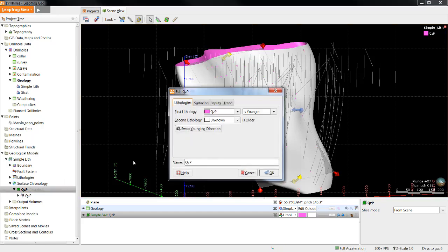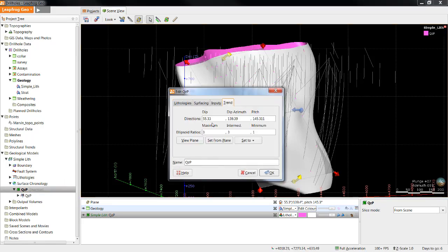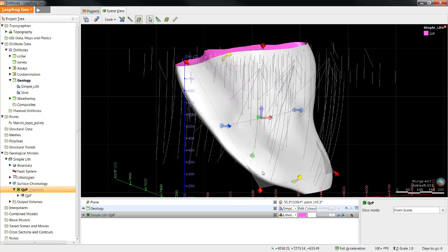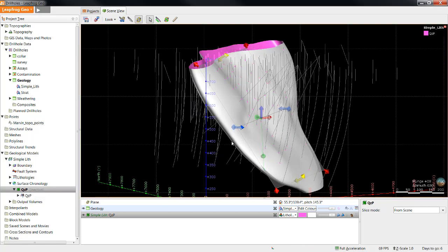But if you didn't want as much stretch, you could easily drop the maximum and intermediate values down to 2 or 1.5, and it would still add a trend to the surface. It just wouldn't be as strong. This is obviously a simple approach for dealing with a simple trend. Frequently, trends are not this simple. They bend and fold in XYZ space.